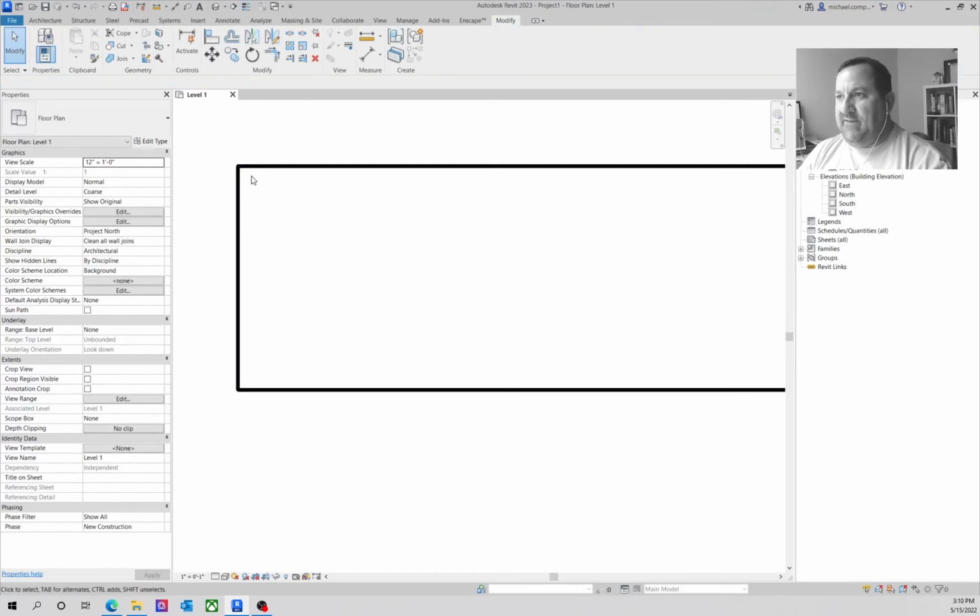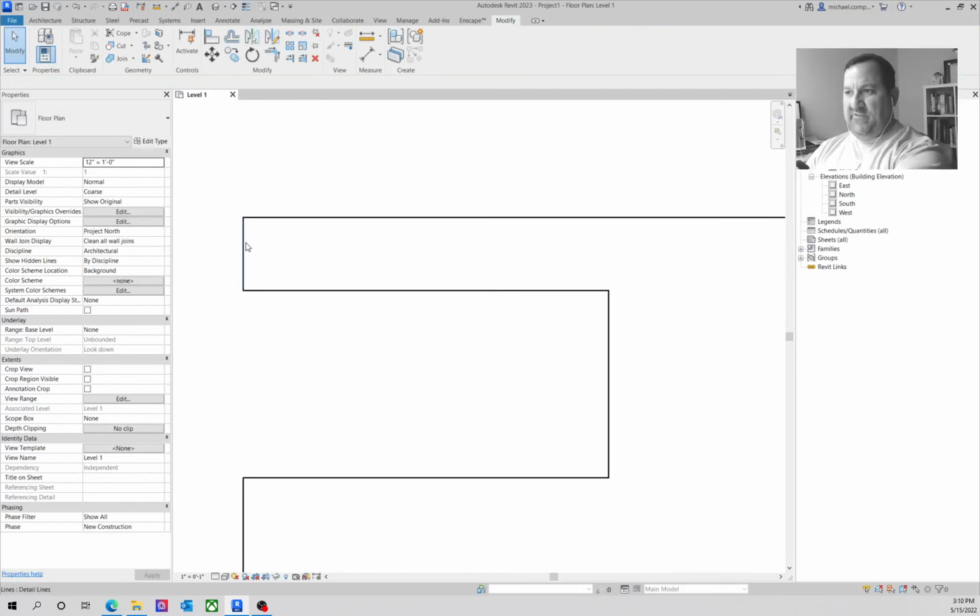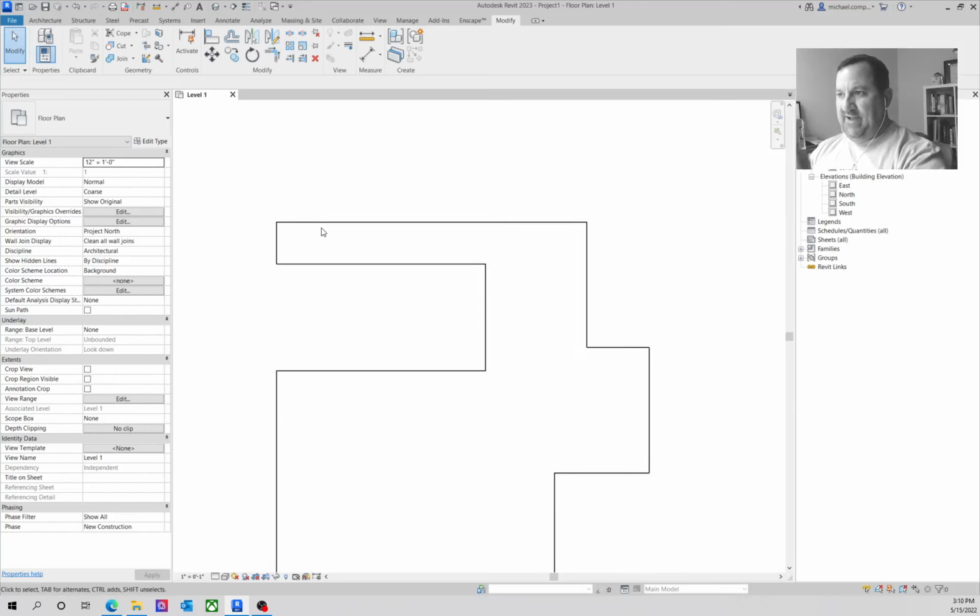So see how thick that line is? That represents a cut plane. That's a line thickness of the plane you're being cut at. And if you watch the other video that I gave you as part of this assignment, where it talks about the line weights, the different types of graphite and the weights that they represent, this would be your soft 4B or 2B or something like that.